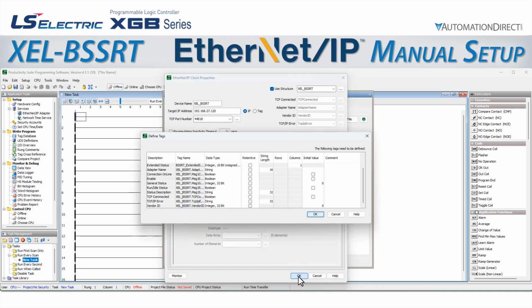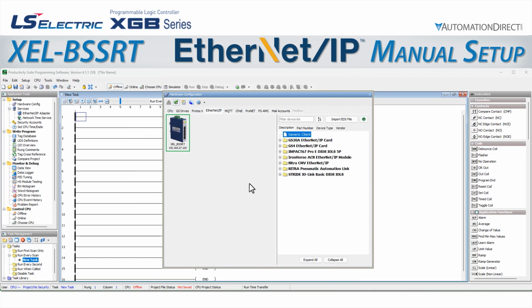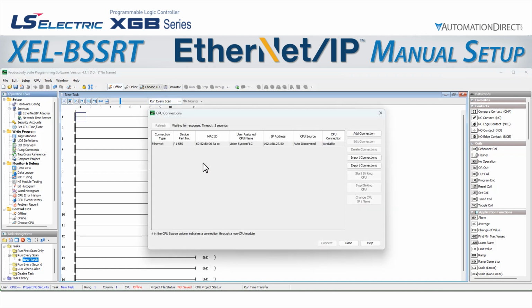Let's click OK, and it will prompt us to create all the structure tags for the Ethernet IP client properties. We will leave them all at the default and click OK again. We can now see our XEL-BSSRT at IP address 192.168.27.120. Let's close out of that window and choose a CPU for this project to connect to.